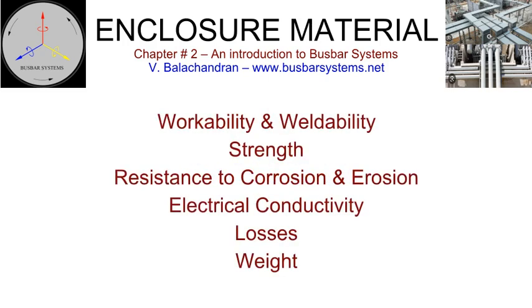To be cost-effective, the enclosure material properties must consider workability and weldability. Fabrication of enclosure comprises shearing, punching, folding, and welding. The process can be manual or automated and contributes significantly to the cost and performance of the product.